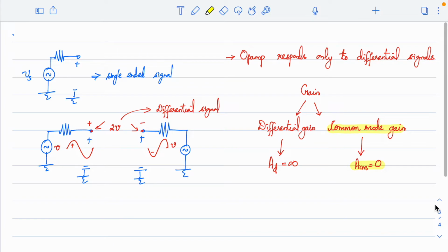When I say common mode signal, say for example, in an IC or any circuit, the common disturbances such as noise, whether from the power supply or from other sides, will affect all the nodes in an IC in an equal way. For example, a disturbance from the power supply line will affect every point in an IC in a common way.